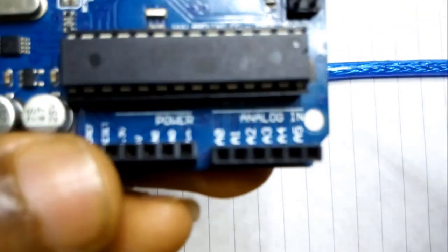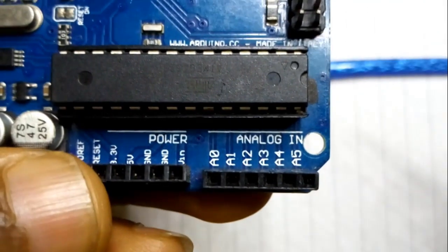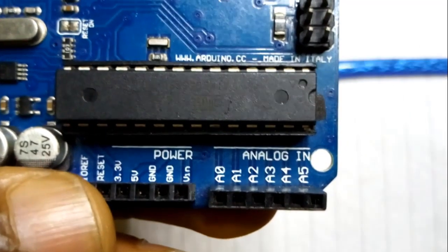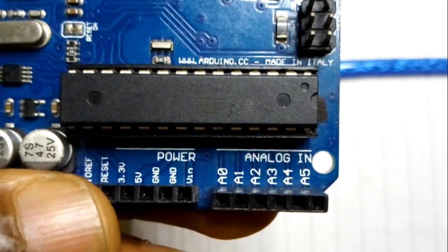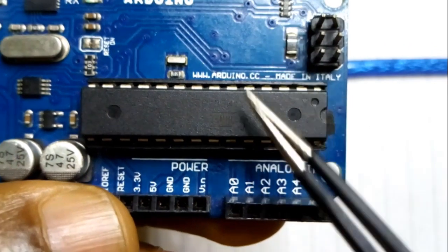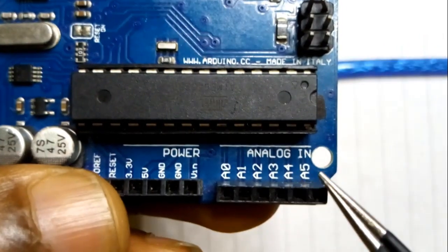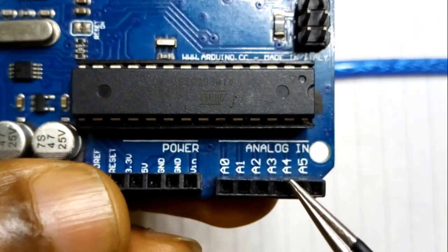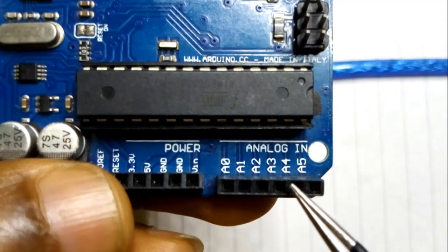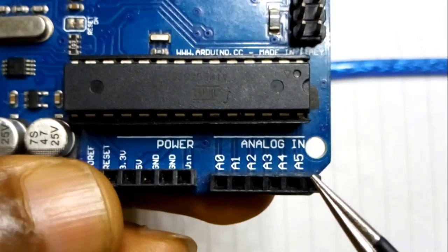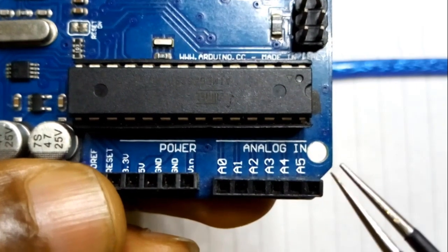There is also another form of communication protocol called the I2C, or twin wire communication protocol. Arduino Uno is also capable of this communication. It is also a means that Arduino can communicate with other devices. For the twin wire communication protocol, the Arduino uses just 2 pins, and here it uses analog pin A4 and A5. Analog pin A4 serves as the SDA, or serial data line, and analog pin A5 is used as the SCL, or the serial clock.